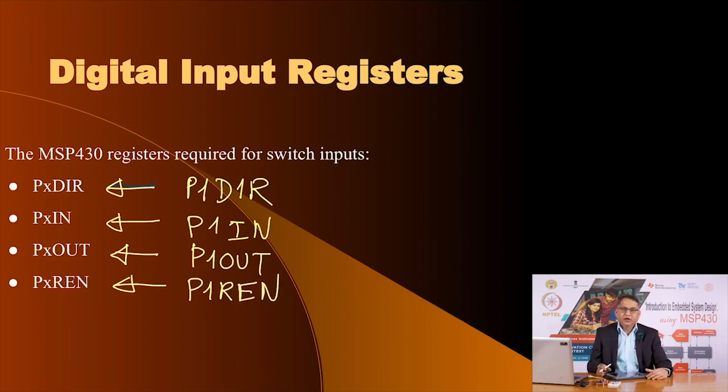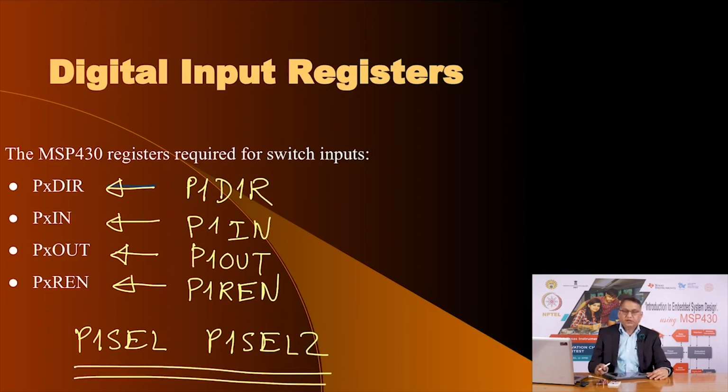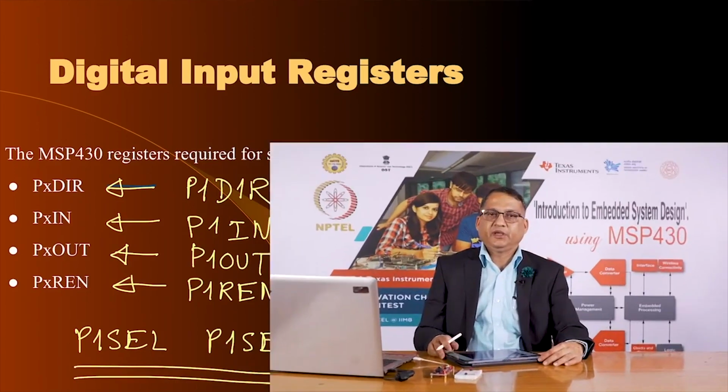So, these are the registers that we need to deal with. There are other registers, P1 SEL and P1 SEL2, but these are only utilized when we want to invoke alternative functions on a given pin, and since we have decided that we want to use this pin as input, we are not going to be bothered by these two registers. We will not use them in our program.